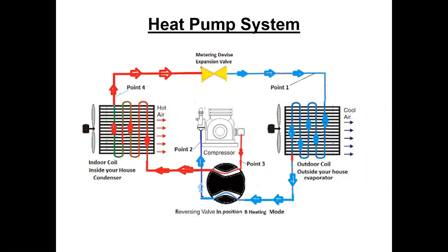You know, they can put variable speed fans on things so that you can modulate the fan speed, right, so they can control the refrigeration system a little bit independently. And so, where the optimization is on that right now, I'm not sure. Like on my systems that are cheap, the fan just clicks on and clicks off. And when the fan clicks off, the compressor clicks off. And so they just kind of come on and off together.